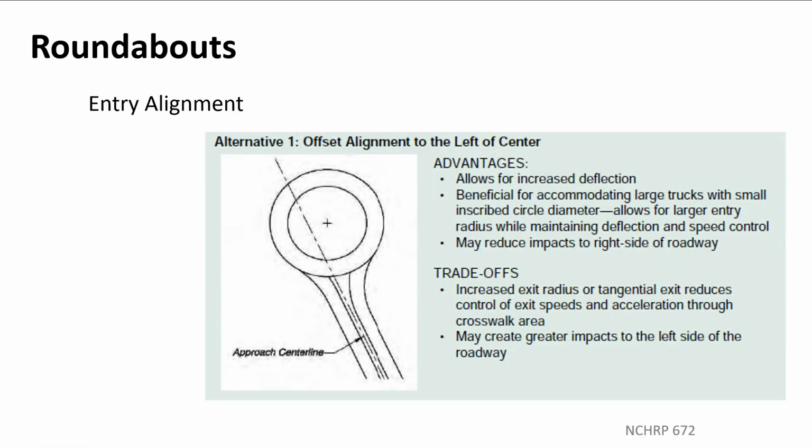So a very tight urban intersection is often not a good choice for a roundabout because of that need for space right at the intersection. If it's a more open intersection, then you can probably get a roundabout to work pretty well and actually save right of way further away on the approaches.